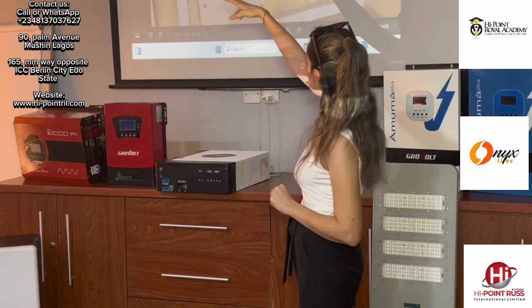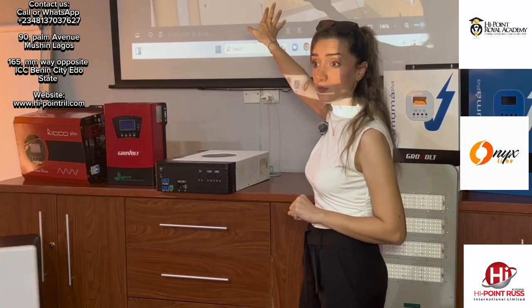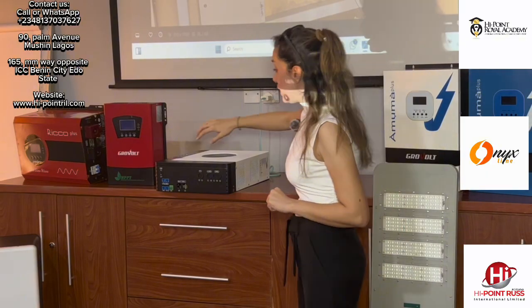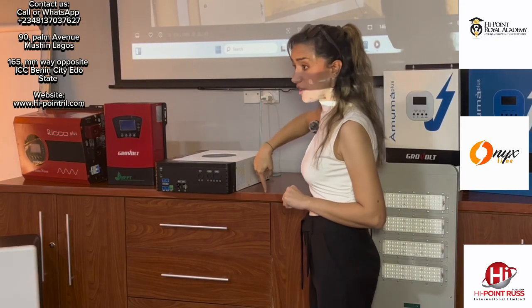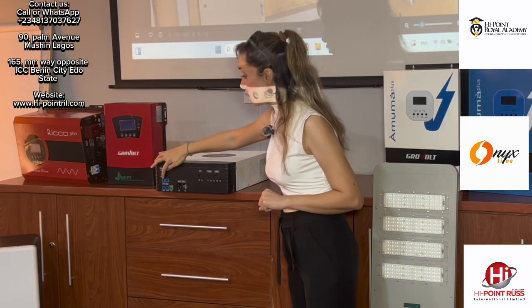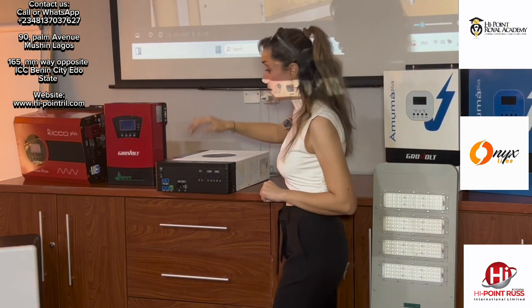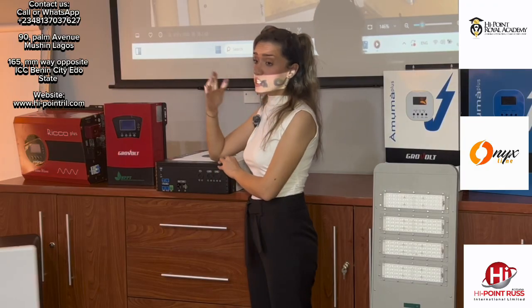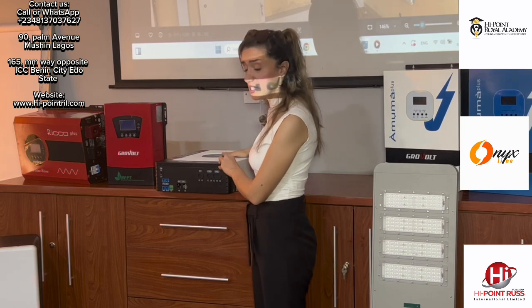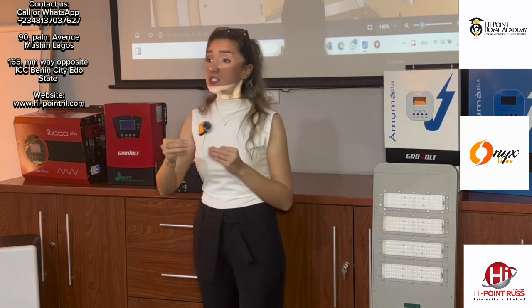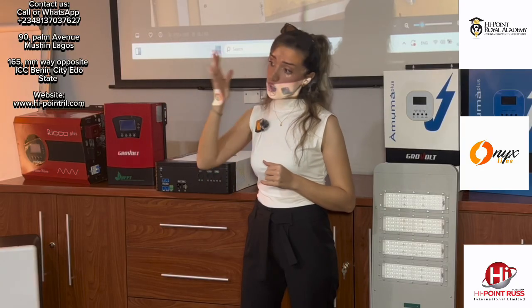Okay. So see now here it's 6 inverters, 36 kilo. This is a parallel. Let's come again. Parallel from the second port to the first port. Then I will close the beginning and the ending of the inverter by RG. This is about the parallel communication cable. Then I will go to the settings in the inverter and set whether it will work in parallel as single phase or 3 phase.